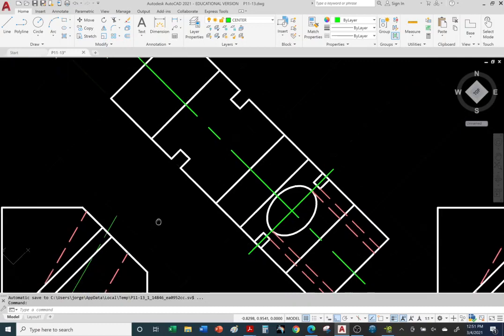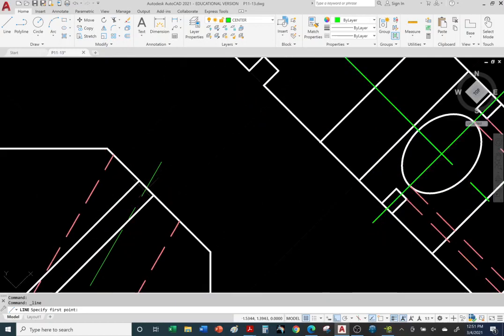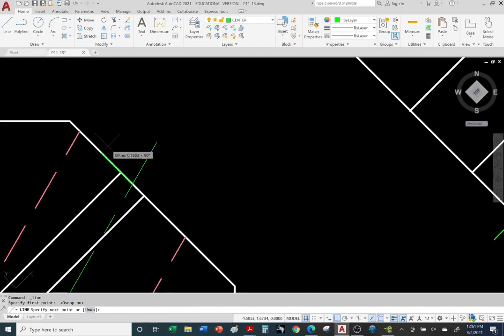And now I'm going to follow the exit point of this green center line. Okay, so let's go to center line. So we need to draw one going across. So I'm going to zoom into the front view and see where the green center axis exits the surface, or starts, or hole starts along this surface. So we're going to go to this point here. So let me turn on Object Snap. So it's where the white visible object line intersects the green center line. That's where our center is for our hole with respect to this view right here, or the top surface.